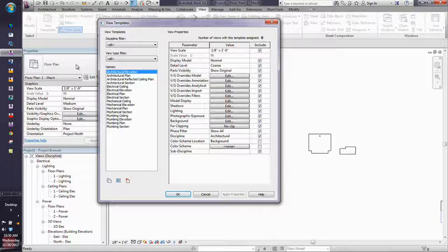If you're in AutoCAD MEP, the command is Create HLR. It's been around since Architectural Desktop Release 1. It's an old school command. Region will also do the same thing if you have a 3D solid.